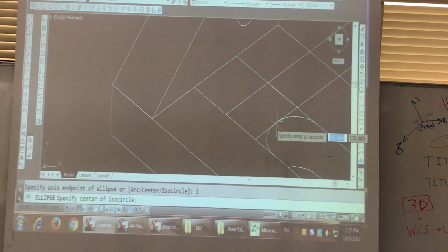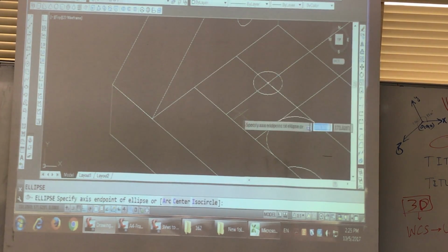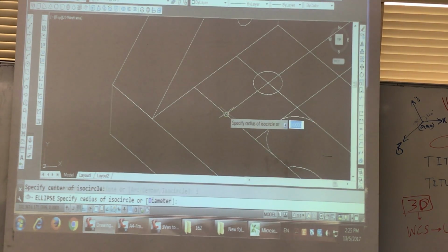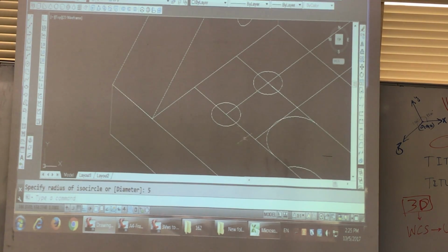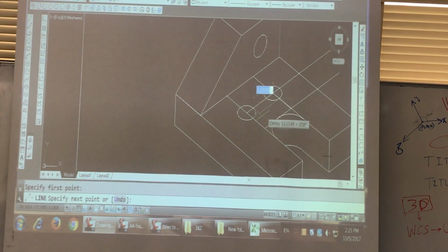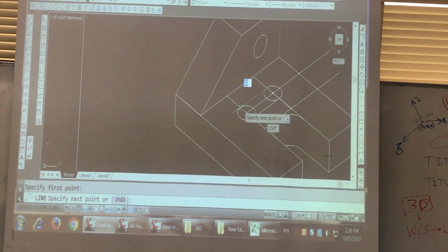See, when I draw, this line did not become perfect. Anyway, just for demonstration, it doesn't matter. You can draw. Is it drawing correctly? No. So press F5. This is the circle, radius 5. Again, I for isocircle, enter, this is the center, and draw it with a radius 5. Isn't it? What I was doing is taking a distance of 12.5 from here to here. Now I will take a line from here to here, join it. Wow. Isn't it? Now, what is it?